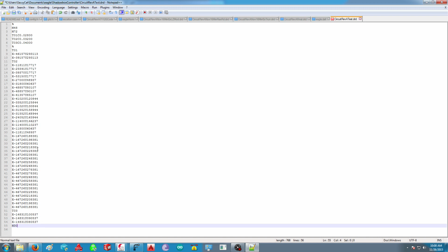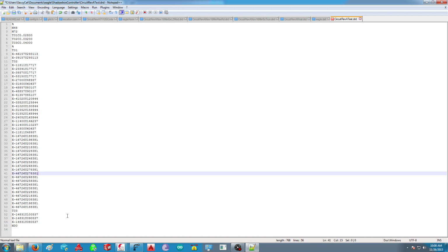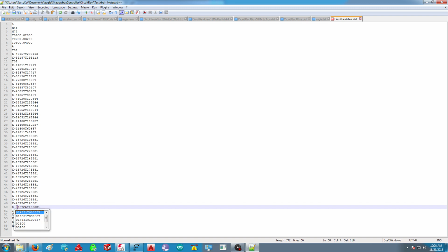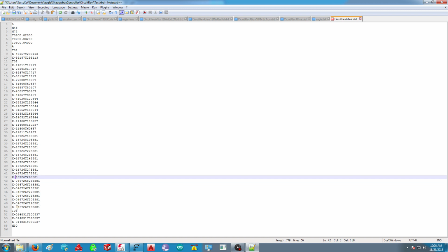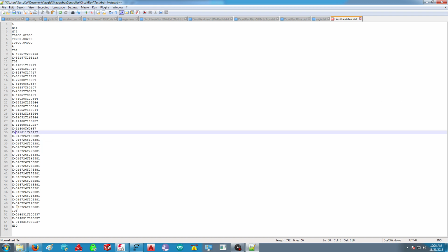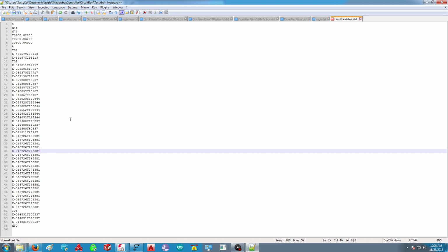So here, the largest y-axis values, all these that are hanging out there far right, have 6 digits in them. So none of these are going to go into FlatCAM correctly because there's 6 digits on the y and there's only 5 on the x. So I'm going through and adding leading zeros wherever they're needed so that every x and y coordinate has 6 digits. I'm just doing 0 left up, 0 left up so that I can quickly breeze through it. I'm sure someone clever could write a script to do this automatically, but just for the sake of the tutorial, as soon as I figured this out, I was like, yeah, people need to know.